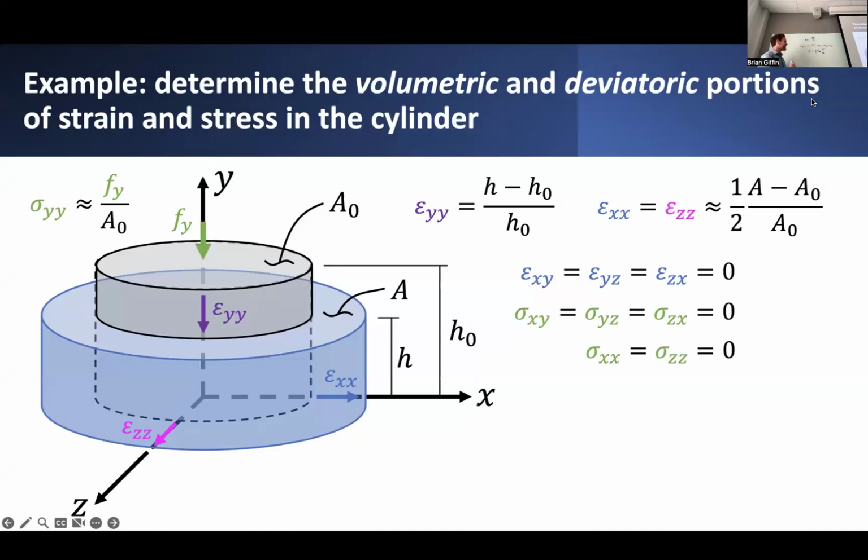So you basically just need to take the original strain tensor and then remove from the diagonal entries of that strain tensor 1/3 of the volumetric strain. Fairly easy. So basically remove the average part of the total strain, and that's how you get deviatoric strain.